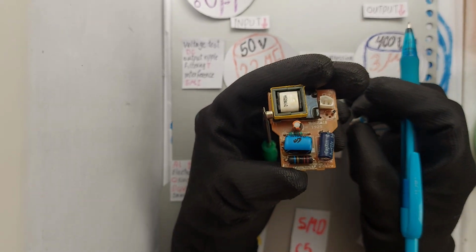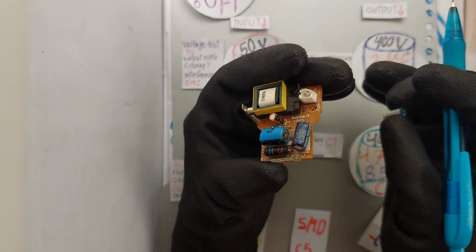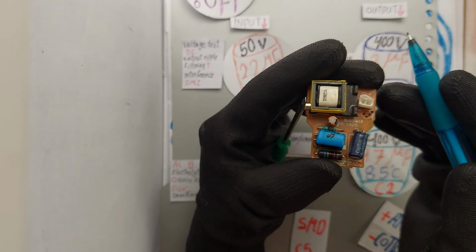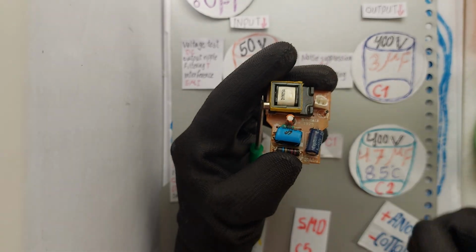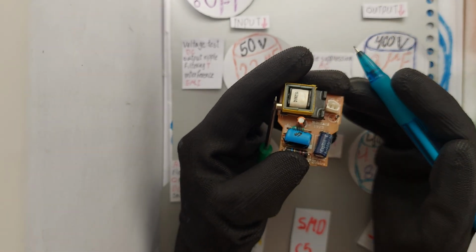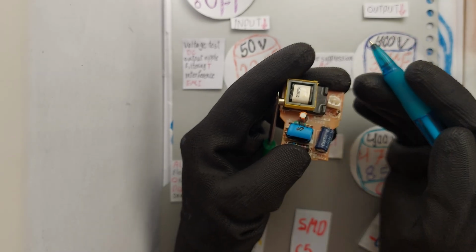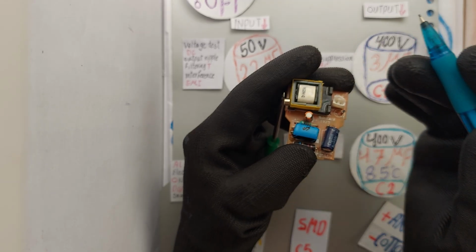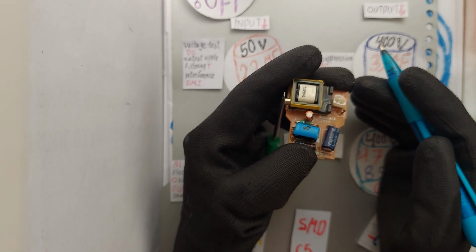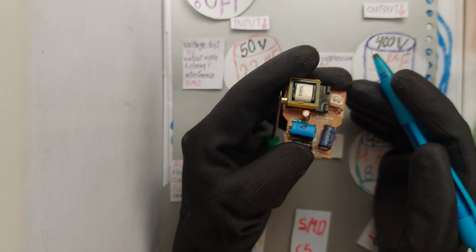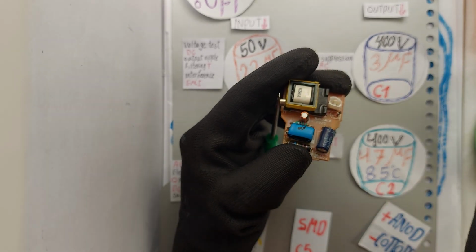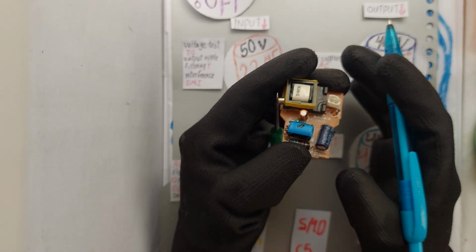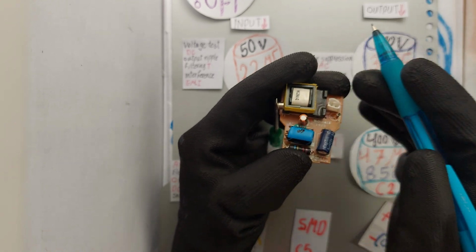Let's see what characteristics each has and why they're placed on this board. At first, capacitor 1, here. This large capacitor is on the primary side of the circuit. After the diode bridge converts AC to DC, C1 smooths out residual AC noise and filters the DC voltage. Its 3 microfarad capacity and 400 volt rating indicate its ability to store energy for the transformer. This capacity and voltage are chosen to handle high input voltage, for example 220 volt AC, and provide stable energy